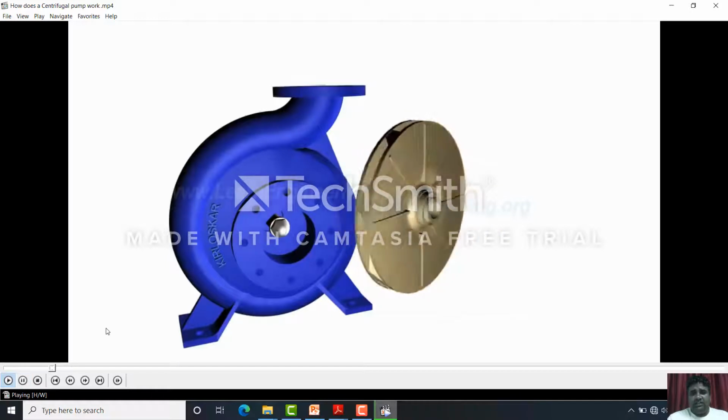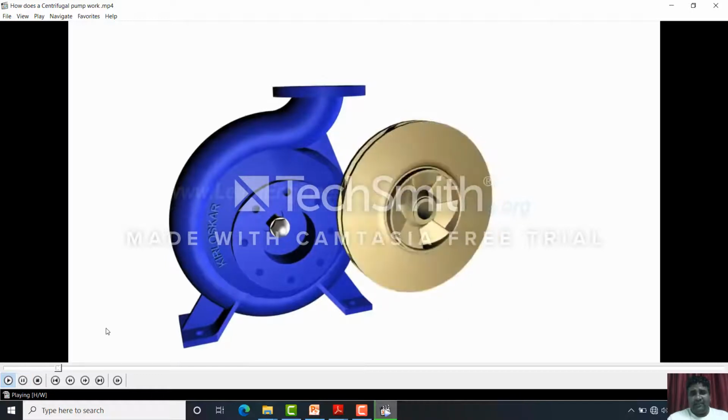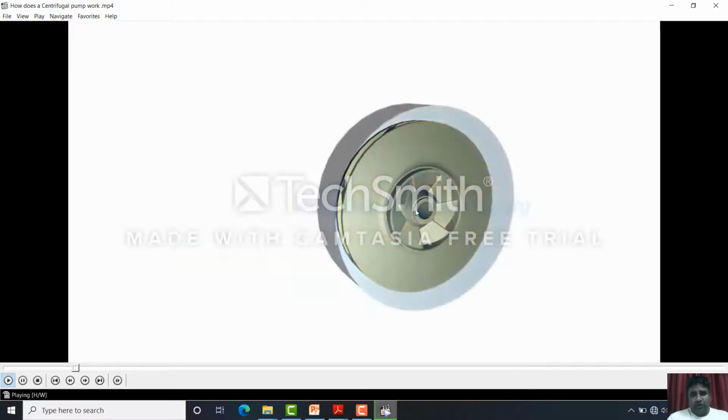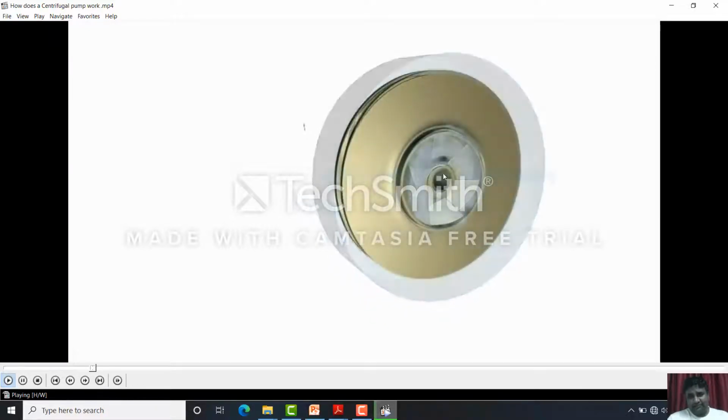So this is the disc which rotates inside the casing. It has got a series of curved vanes fitted inside shroud plates. So when the impeller is rotating, immersed in water, when it starts rotating, it creates a low pressure here.